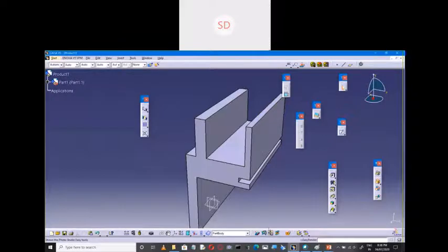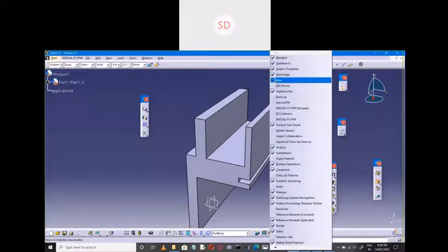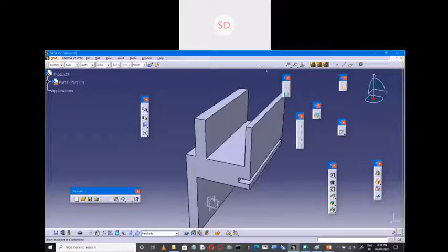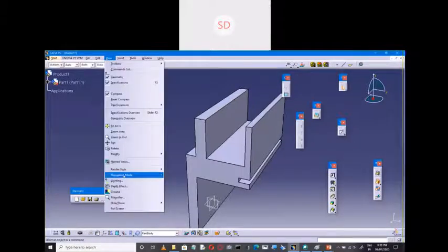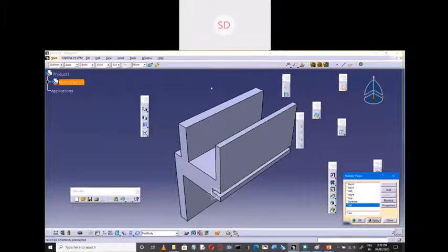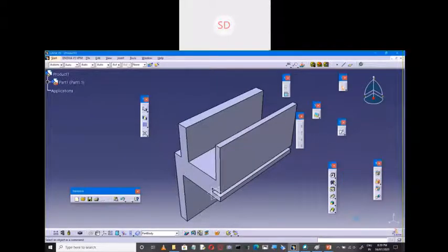Now if you look out the approximate distance, it has taken as 120 here. It has taken 120. Look out. That means from the sketch plane, it has taken a distance of 60 mm on both sides. Actual is needed how much? 60 mm, but now it has been 120.